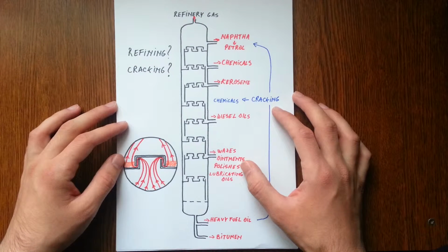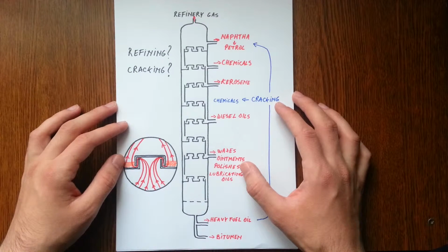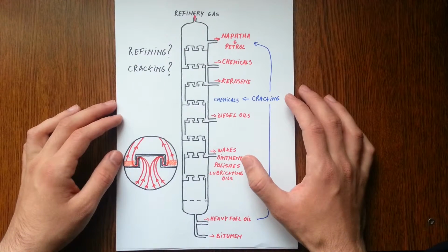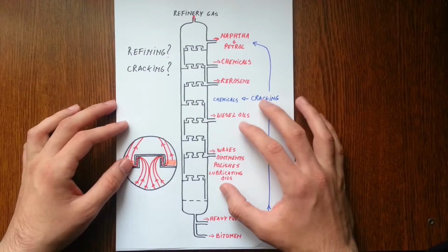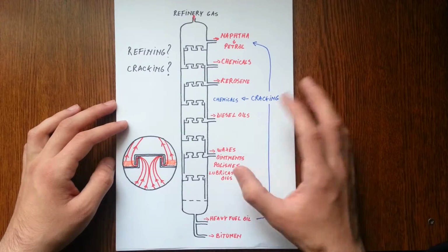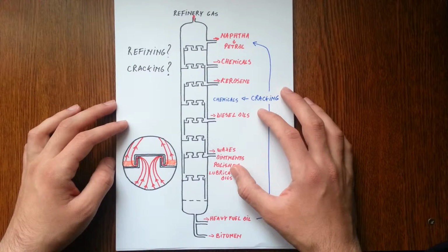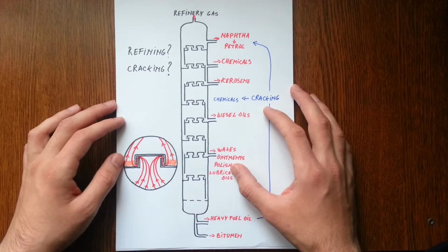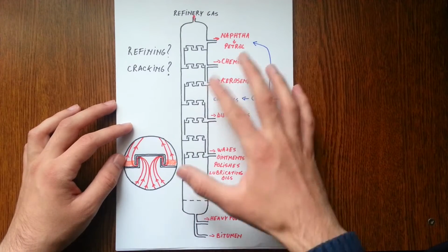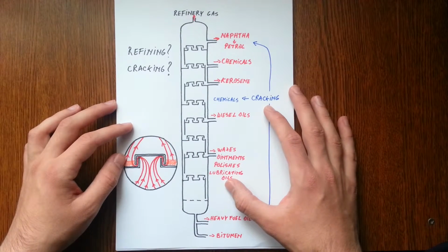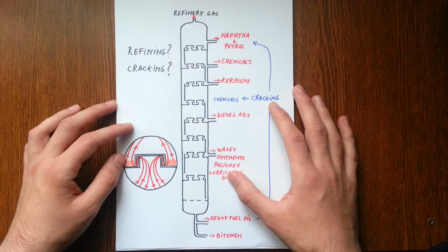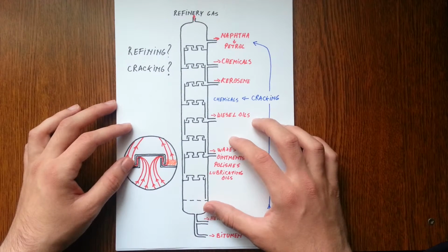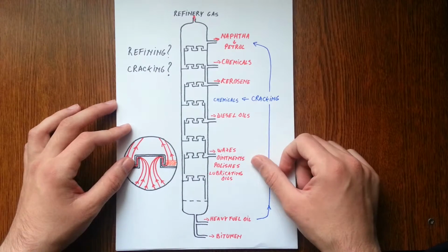Hey guys, so today we're going to see how fuel is made. As you may know, both petrol and diesel come from crude oil, which is a complex mixture of many hundreds of different hydrocarbons, as well as other products which need to be removed during this process of refining. The oil is refined into its constituents by a process called fractional distillation, this one presented here.